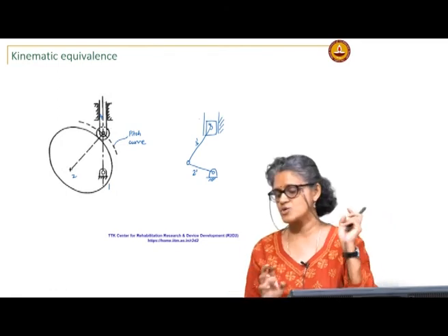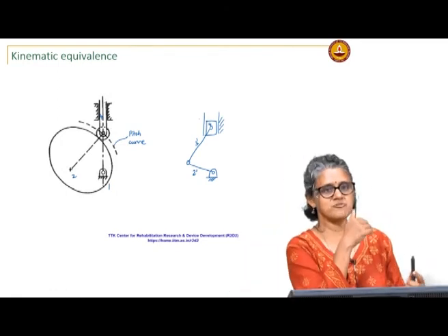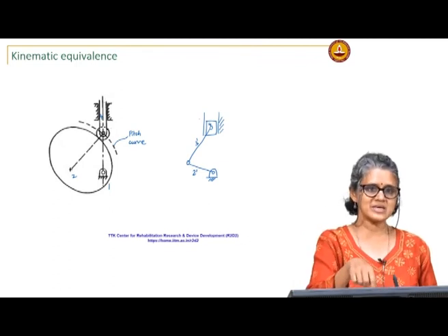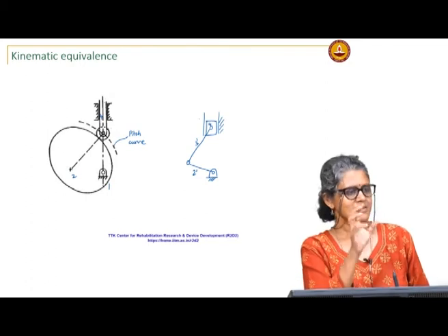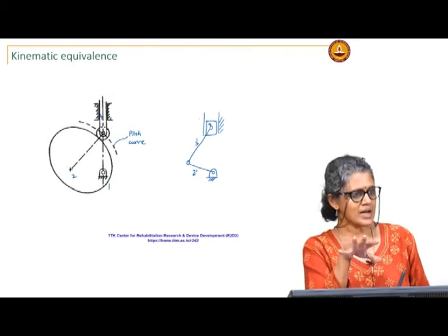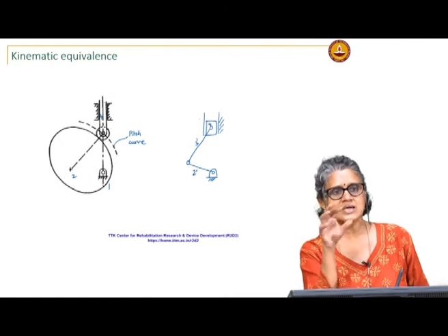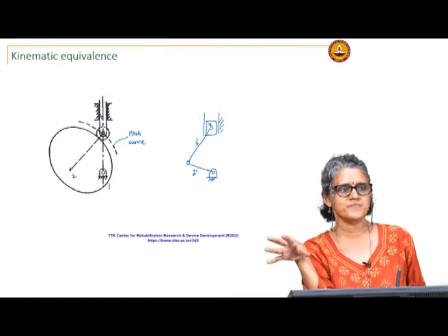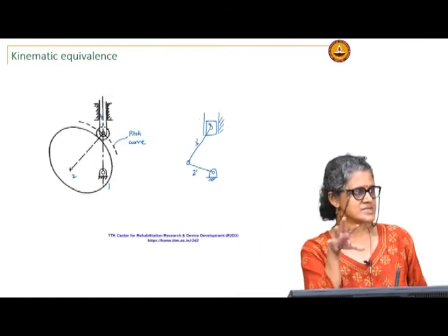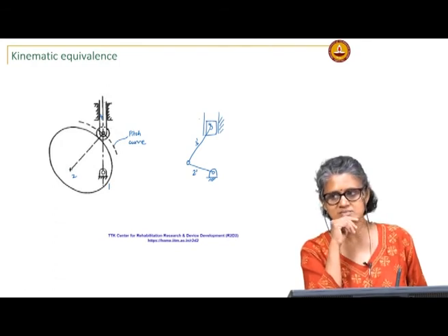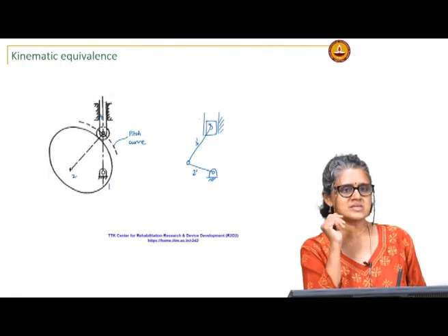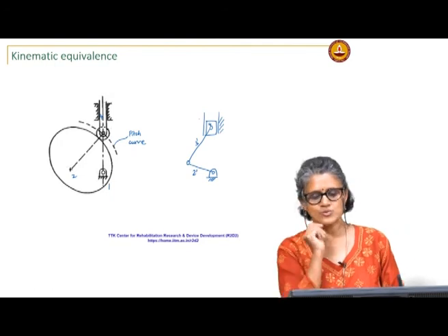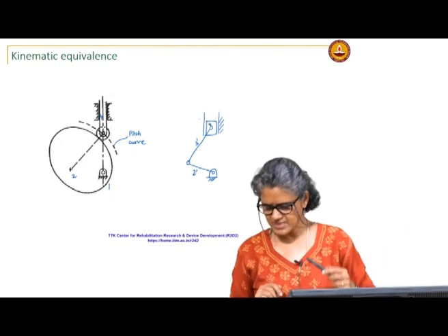Okay. So, with this kind of thing it may be difficult to do, unless you have the equation of the cam surface, that it's a little tricky to do the analysis, but if you are interested say in only certain positions, you are interested in the velocities and accelerations, then for those positions you can represent them by an equivalent linkage and then do the analysis.